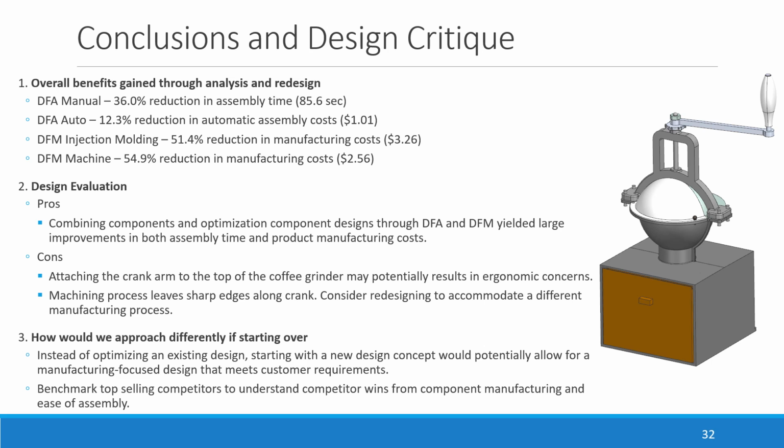This redesign has a reduction in assembly time and automatic assembly and manufacturing costs. However, one potential issue we've identified is ergonomic difficulties may arise from attaching the crank arm to the top of the coffee grinder. Also, the machining process for the crank may leave sharp edges.